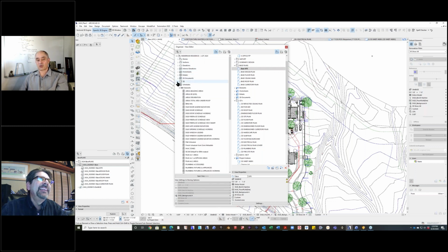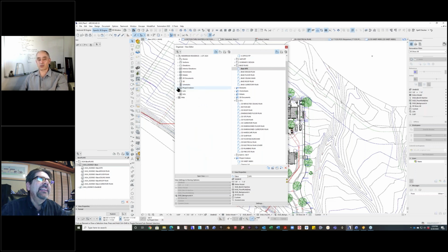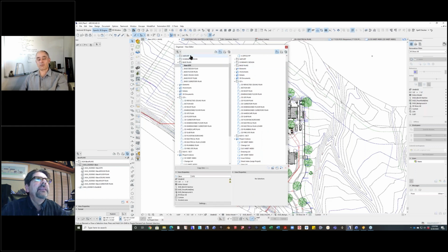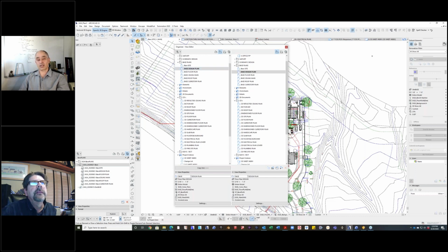And I'm sure some of you are going to go, oh, does he have to explain this? But believe me, I know there's confusion here. So you go to the next one, which is the view map. The view map basically are those same viewpoints, but with certain context, like which layers are on, what scale, and maybe graphic overrides, things like that. Each time you double click on a view, you have a predictable way of looking at your project.